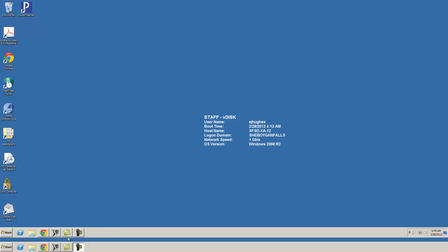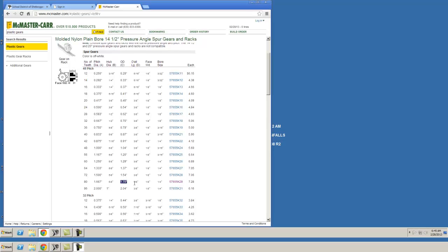All right. Now, the other information you need to derive is, here's the face width, there's the bore size, 1/4 inch, here's the overall length, it's 3/8. So I know that this B diameter, you need that, so 5/8.